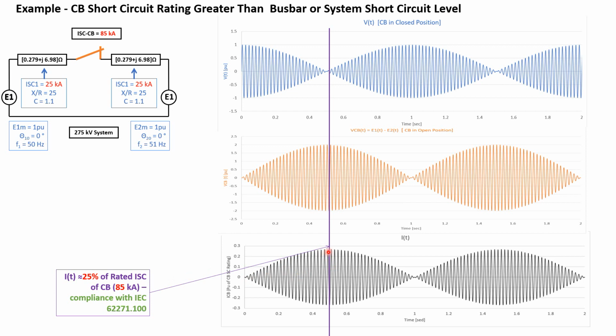So now we can say if this circuit breaker is supposed to interrupt out-of-phase current, and the worst point to interrupt is this point, then we should somehow increase the short circuit breaking current rating of that special breaker if it's required to do this operation.